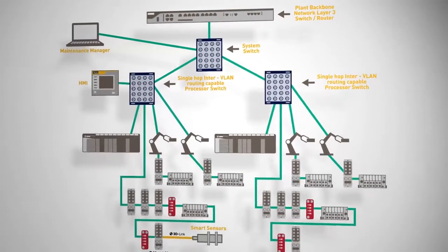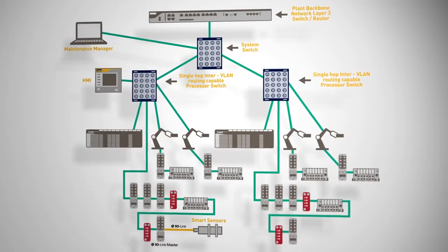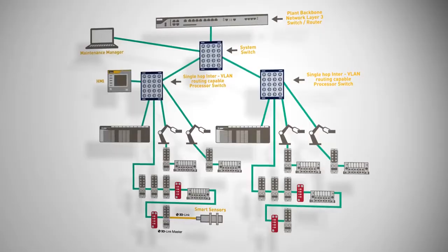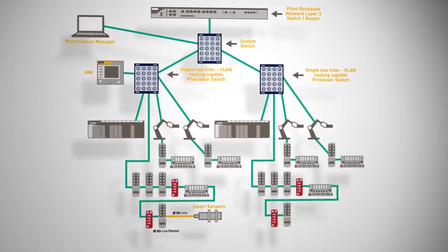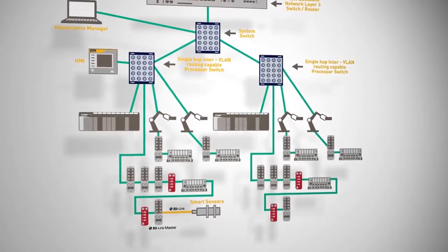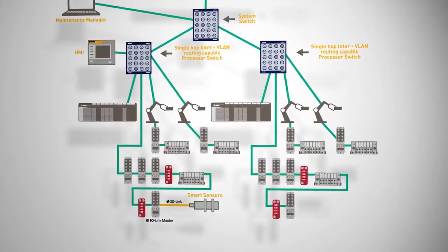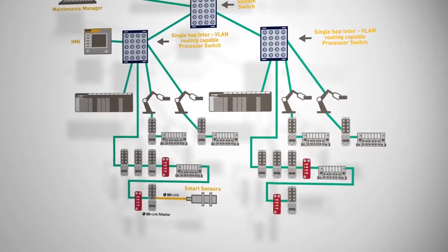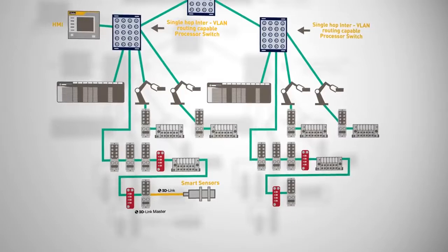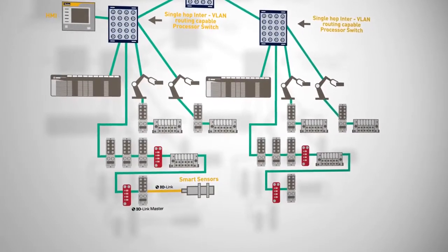So if you look at this screen, as you see, there's 2 PLCs with I/O connected to them. And chances are, it's just like in that robot cell. Both have the same addresses. Them I/O robots would have the same I/O addresses. The I/O blocks would have the same addresses, so that way they could speed up their time in programming. But you don't want the information from one PLC to get to the other. So the information is blocked by the managed switch, so only lets certain information go between the 2 cells, like which model number is coming, or if another car is coming, or if there's an emergency stop.